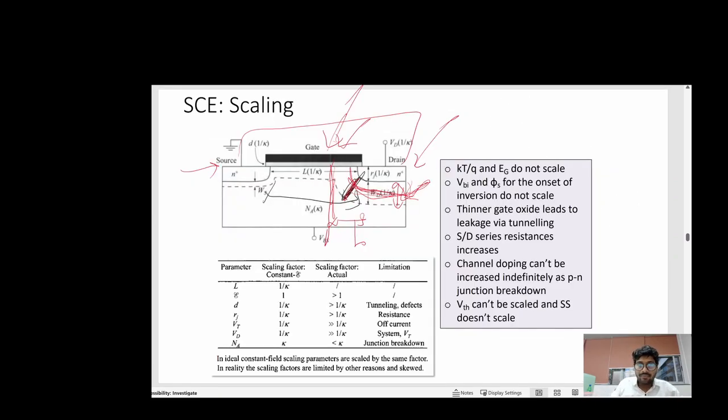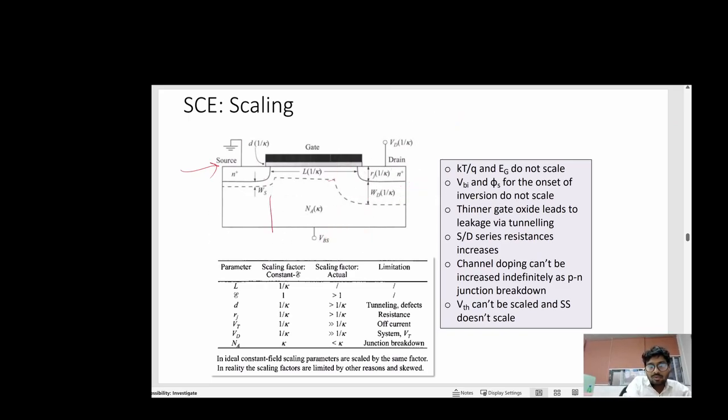So in this one, this was your channel length, and at this position only 1% of your channel length was the depletion region, so it will not be that effective. Okay, that will not affect. If you decrease the channel length to this much, then 50% of your channel length is the depletion region. Okay, that will affect.